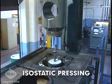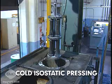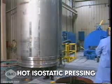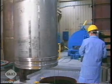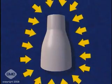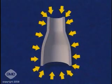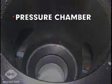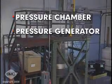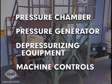Powder consolidation by isostatic pressing at room temperature is called cold isostatic pressing, or CIP. When performed at an elevated temperature, it is known as hot isostatic pressing, or HIP. Cold and hot isostatic pressing applies high pressure to the powder uniformly in all directions, thus producing consistent density. The press for cold isostatic pressing includes a pressure chamber, pressure generator, depressurizing equipment, and machine controls.